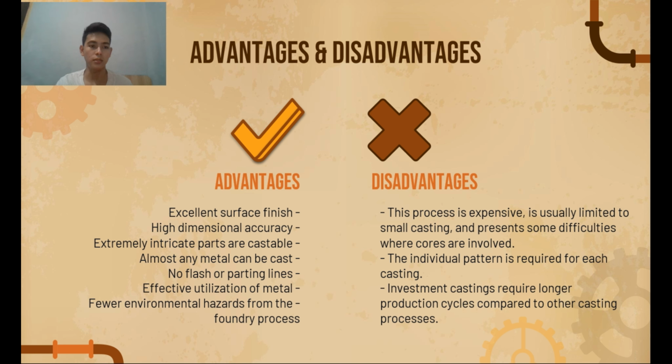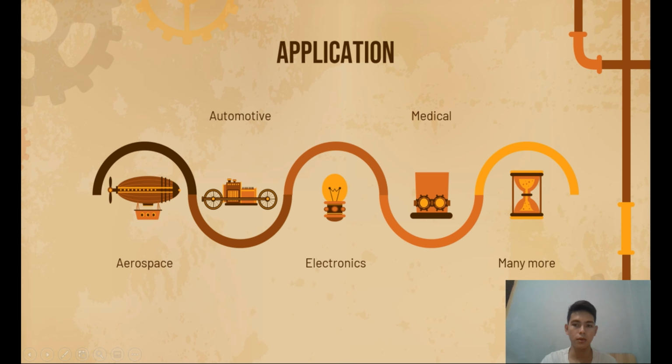And then the disadvantages. This process is expensive, is usually limited to small castings, and presents some difficulties where cores are involved. Next, an individual pattern is required for each casting, which leads to investment casting requiring longer production cycles compared to other casting processes.